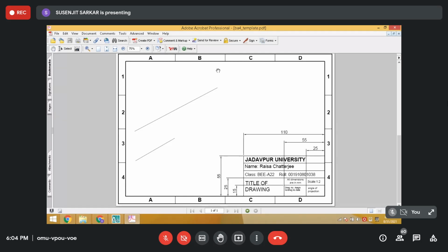We have changed the shape of the points, right? We have understood the object snap and the ortho command. We have drawn the vertical lines, the grid lines, horizontal grid lines. We have also created texts for grid naming, like 1, 2, 3, 4 or A, B, C, D, right? We have completed this part.